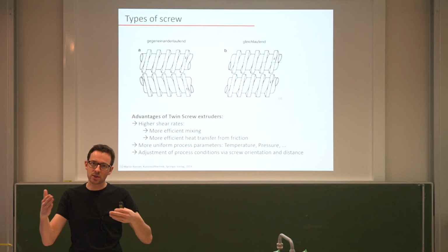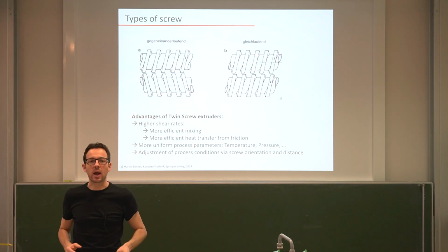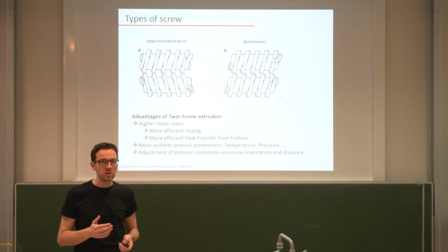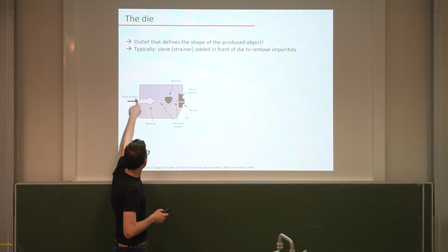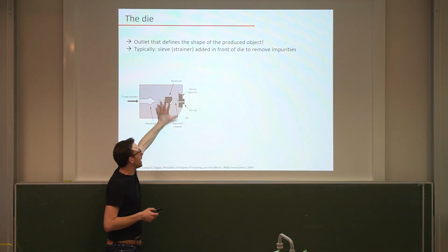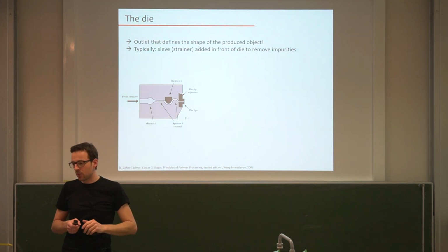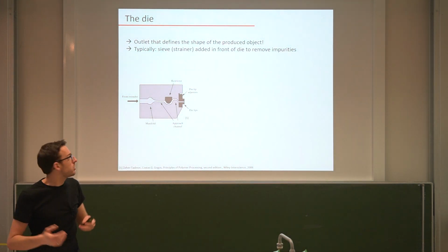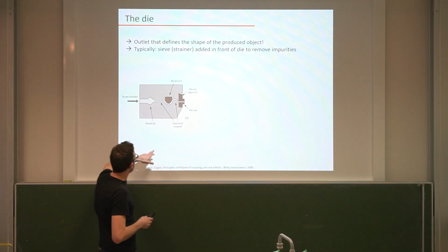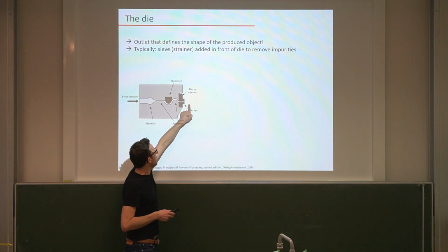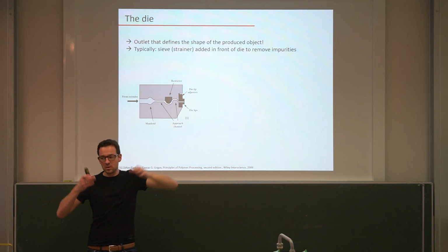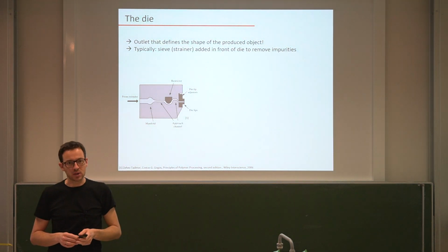Okay, so now at the end of this extrusion process, we have a polymer melt that is homogeneous. The viscosity is adjusted in a way that it comes out of the die in a somewhat regular fashion. And then we approach the exit. So here's the extruder. We go through some parts where we can have filters, for example, to remove any impurities and adjust the viscosity while it approaches the die. And finally, it comes out of these die lips to get a defined cross-section.